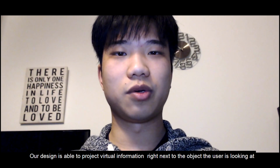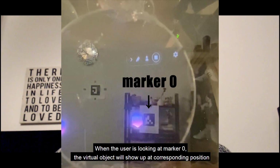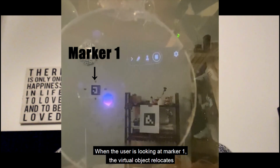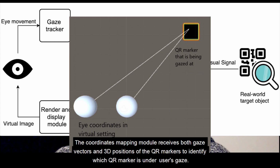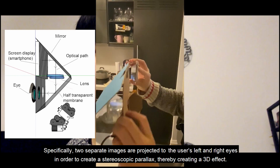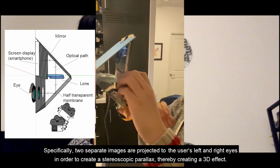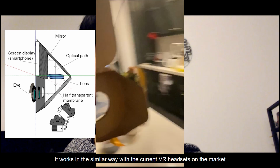Our design is able to project virtual information right next to the object the user is looking at. And when the user moves gaze to another object, the virtual information changes accordingly. The coordinates mapping module receives both gaze vectors and 3D positions of the QR markers to identify which QR marker is under the user's gaze. Finally, the render and display module projects corresponding virtual images to the user.